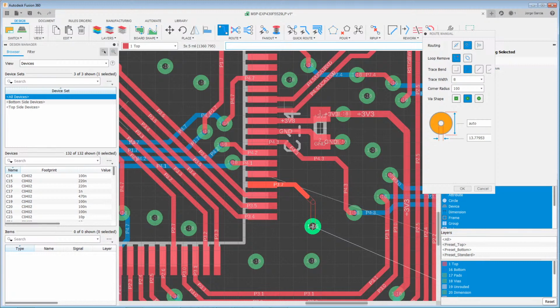and you want to place the via but you want to stay on the same layer, you hold shift and you left click, and now you stay on the top. Okay, that can be useful if, for example, you are dropping down to a ground plane but you're going to interconnect multiple components to a single via. That's where this comes in handy. Okay, so keep that in mind. You hold shift with the via active and then you can place it down.